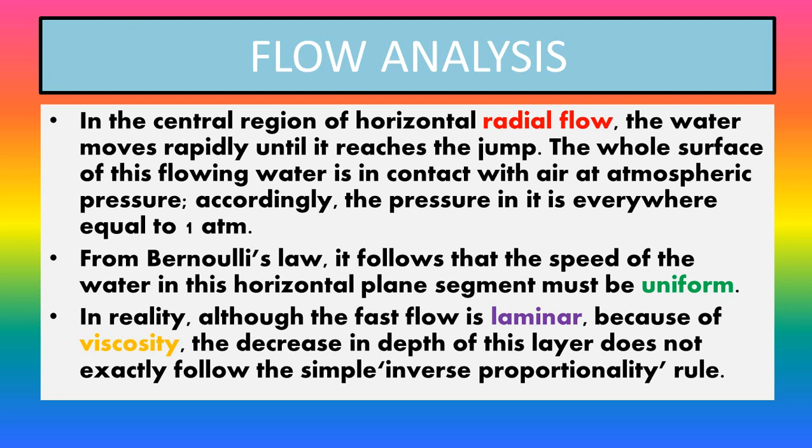In general the flow which is observed here is laminar due to the viscosity, and the decrease in depth of this layer does not exactly follow the simple inverse proportionality rule. Now what is this inverse proportionality rule? The inverse proportionality rule is the continuity equation applied to the flow. You can see that the continuity equation is applied here.